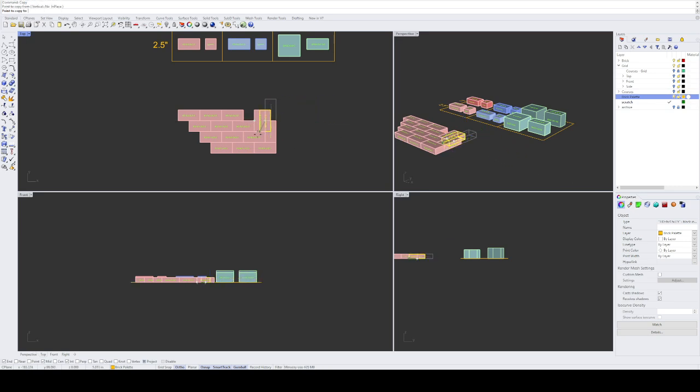And if I select that corner and I snap to anything here, if you look down in the front view when it's moving around, see how it never moves vertically? Even though it's snapping to all those points, it's only snapping in the top-down view. It's not changing where that block is moving in its elevation.